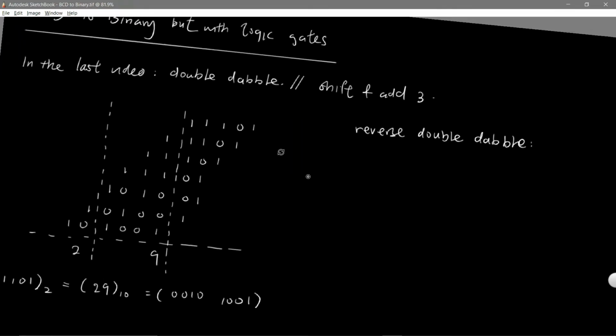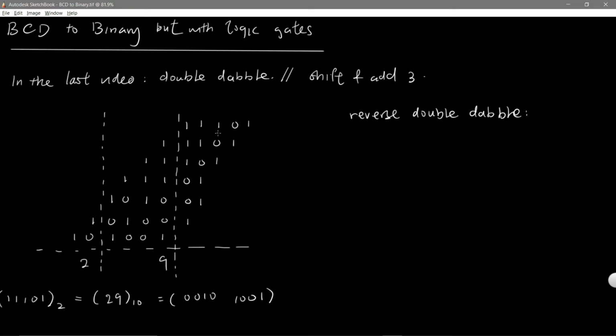So before today's content, we actually have the double dabble, which looks like this. You can also know it as the shift and add 3. It revolves around two operations, shift and add 3 to the values of it. So you want to shift your values to the left. Every single shift to the left is one bit, and it may cross into other columns as shown below. This is the binary values column, this is the ones column, and this is the tens column. And as you know, binary coded decimals are coded in 4 bits of binary values, each representing a single digit in decimals.